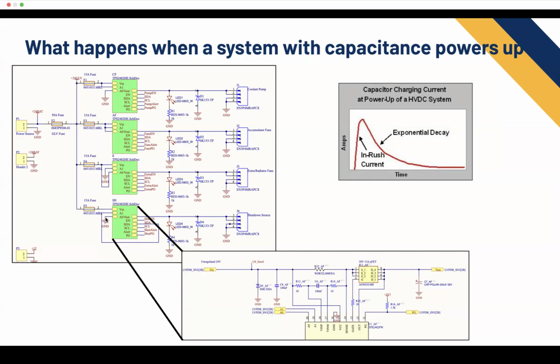An important thing to note about real fuses that burn is that they can take spikes of current. It depends how high that current is, it depends how long the spike lasts for, but real fuses don't burn instantly as soon as you hit the exact number. It says on the data sheet how long it takes to burn at what voltages, at what currents, at what temperatures. But this would probably burn that.